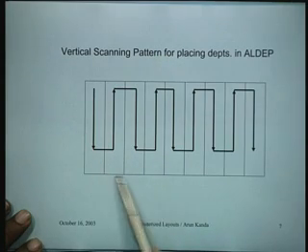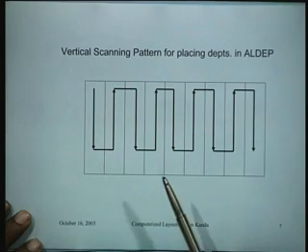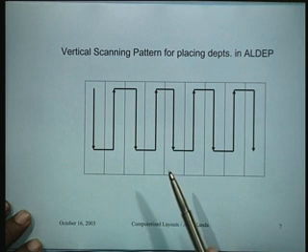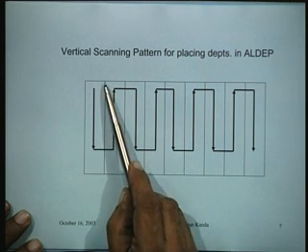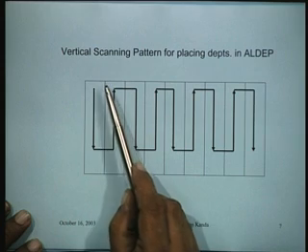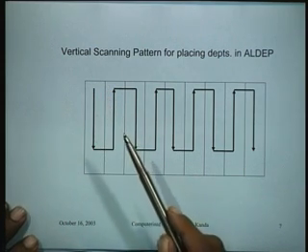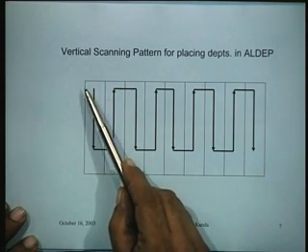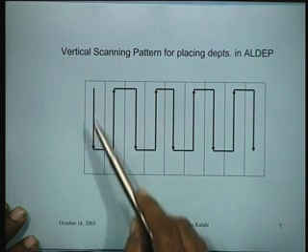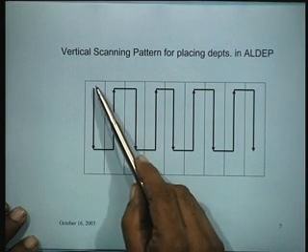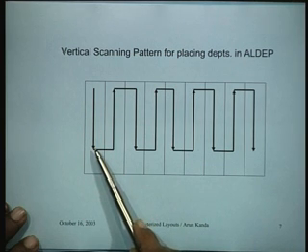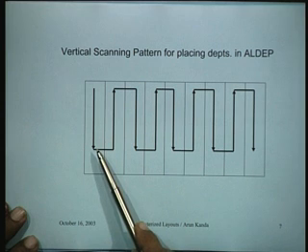One other feature of LDAP is how it places the departments in the layout. Suppose this is the area in which you want to develop the layout. What it essentially assumes is that there is a constant width, and suppose you want to locate a department, it's like saying that this is the width of a sellotape, let us say, and you keep on unrolling the sellotape in this direction, and you know the area of the department, so you can find out what length of the tape you need to represent the area.